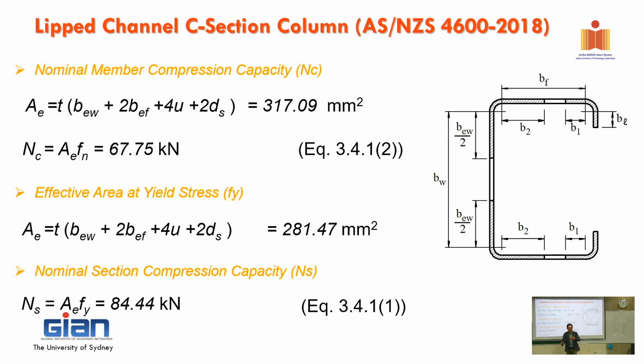It has some buckling, or some member capacity in that one. So in engineering, you need to make sure that those are very similar, then you maximize the section. You don't want to design a very strong section, but it just buckles in the member capacity. So that is how it works here. Okay. Any question?